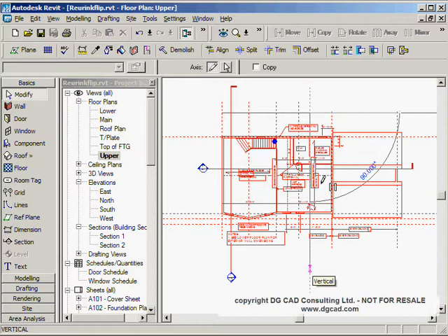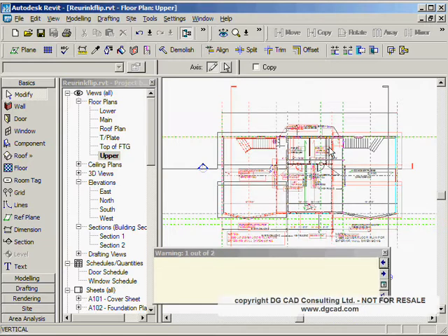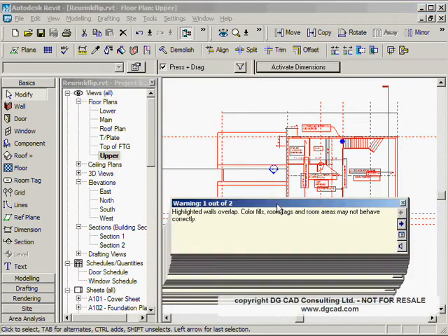Basically doing the mirror now as we speak, and you'll see down here in the lower right hand corner that it's processing and creating all those different views. Okay, we do have to go in and do some cleanup after this is done. Sometimes these section marks don't come out right, and any callouts that are drawn in these section marks you'll have troubles with those. But for the most part, the model has been mirrored, and all the text in the floor plans at least will be there, and we're going to get a warning here.